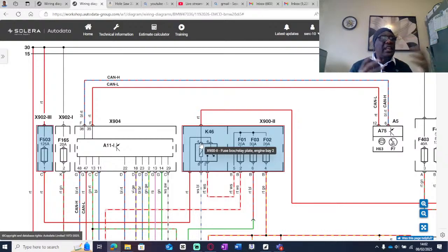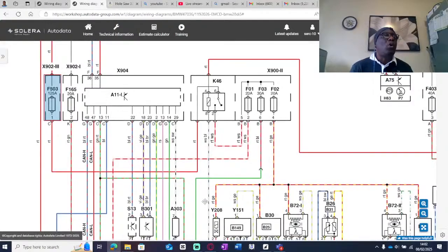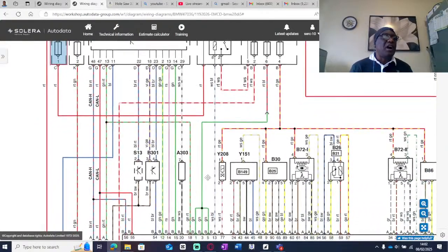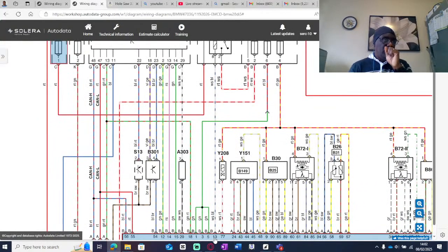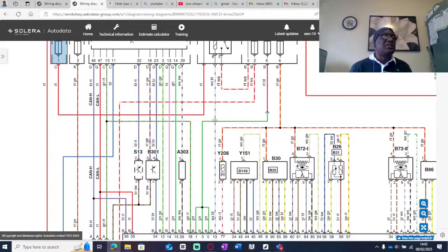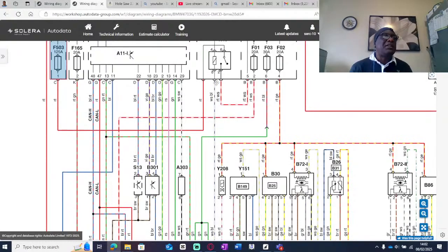But if it's not working, it's possibly because there is no ground. This wire is broken, or the driver in here that provides ground is dead, and you don't have a ground. That ECU will not work. Your engine will not start because there is no ground on pin 8. You can have the 2 powers.